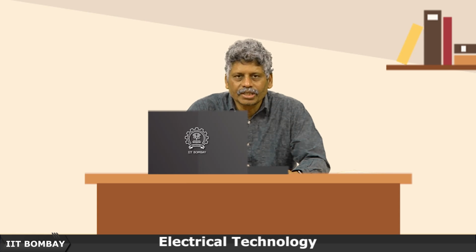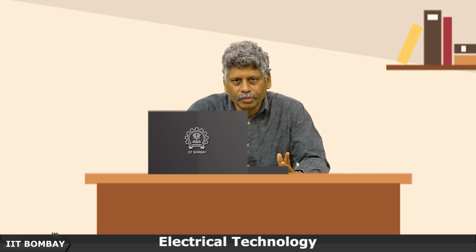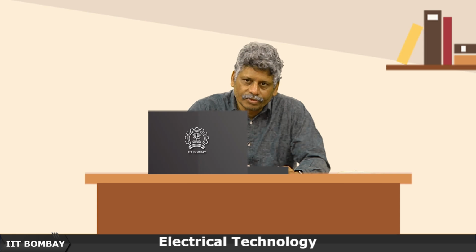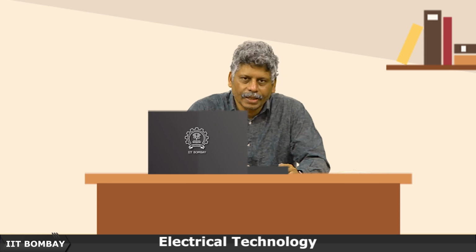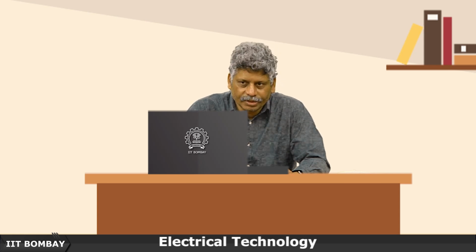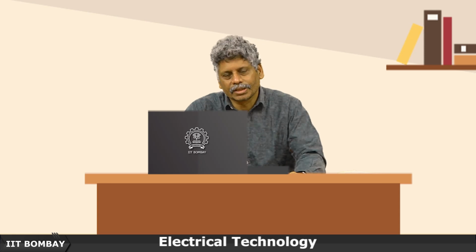We also want to know the efficiency during operation, we want to know the voltage regulation, that is when we connect supply close to nominal voltage at the primary, whether the secondary voltage will be close to nominal or not. Otherwise, the equipment which is connected there as load will not function satisfactorily. So, all this means that we need to know transformer parameters and losses. Losses for efficiency, two losses, copper losses or I square R losses, and iron losses, that is hysteresis losses and eddy current losses.